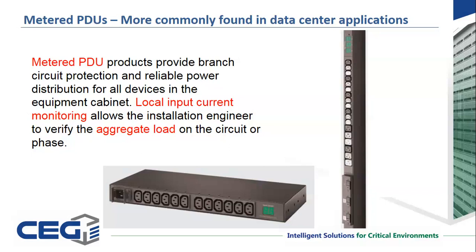So there's pictures here of a horizontal and a vertical. What's cool about this vertical one, going back to the three-phase, remember I said that the manufacturers are doing some things today to help prevent that imbalance, to improve the load balancing. This particular manufacturer uses 3 different colors of outlets: a white, a gray, and a black. That represents the blending of those 3 phases, and it repeats.